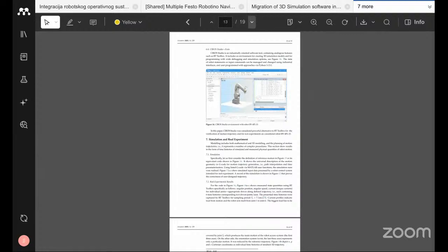This is called Cirrus Studio. This is factory simulation software. The majority of the capabilities are related to the RT Toolbox. Here we can completely simulate a factory model. Also, we can do 3D robot simulation, robot programming, motion simulation, trajectory verification, program debugging, sensor and actuator simulation, PLC communication, industrial interface integration, real robot connection, virtual commissioning, and production system simulation.